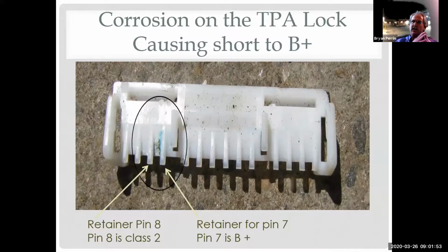I've connected stuff literally this far from a connector because I couldn't get the new pin and I had to save it. I had just a little bit of wire, a quarter inch of wire coming out of the pin, and I either soldered onto it or used a crimp connector onto it and heat shrinked it. And I've never had a problem with loss or heat from that.